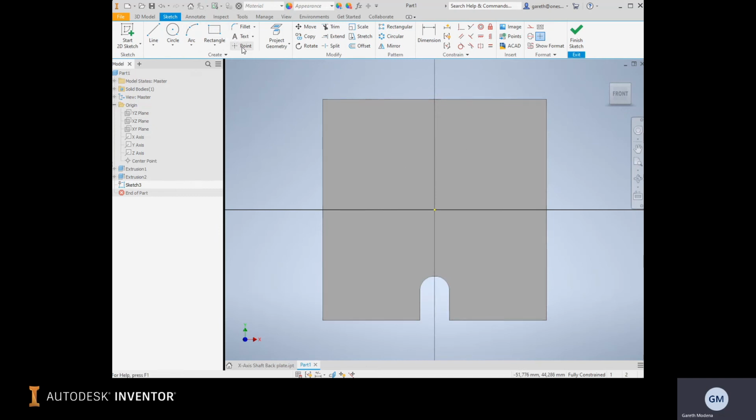In this case, I'm just going to activate the point tool. I'm going to jot down 3 points, roughly where I want them. We're going to make this 15mm from the edge. This one's going to be the same from the outside. Let's go from the inside. So we want to do vertical again. That one's vertical to the center. This one's going to be positioned 10mm from the side, bearing in mind the hole's maybe a 6mm diameter. So we need space for the hole and the outside.